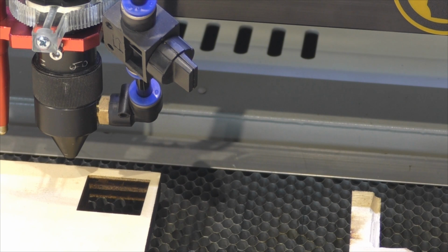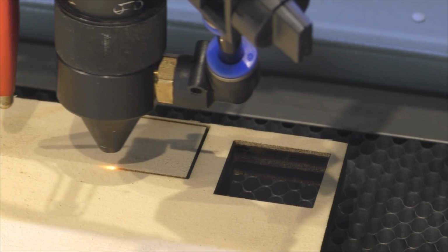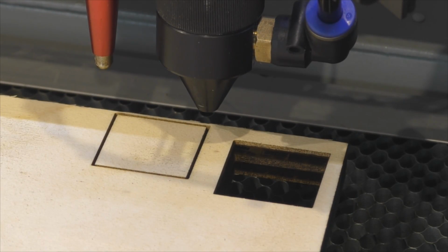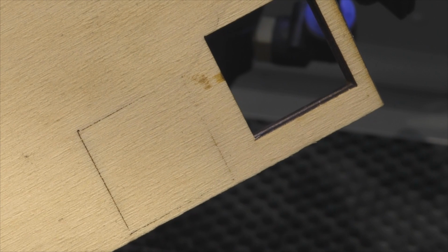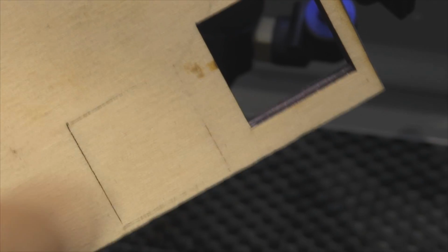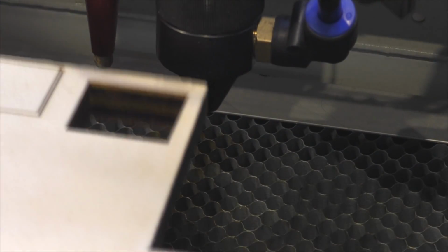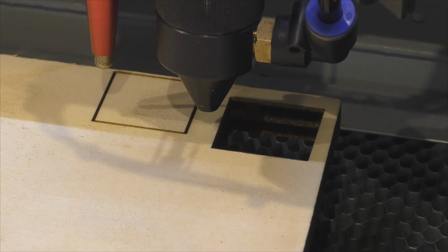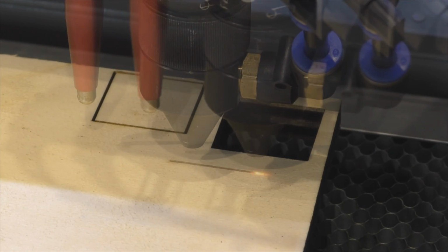Let's go up to 14 millimeters a second. We're certainly looking fairly clean on the surface, and it hasn't cut through. So 14 millimeters is one step too far. We were doing extremely well here at 10 because we had a nice clean cut which told us that we were more or less at the right maximum speed. We could try 12.